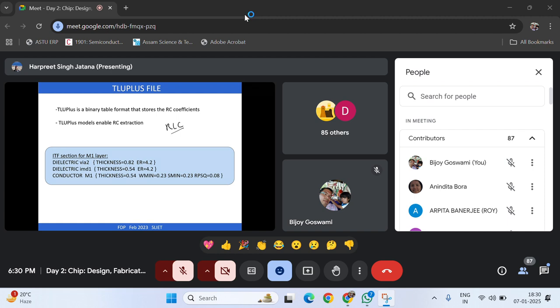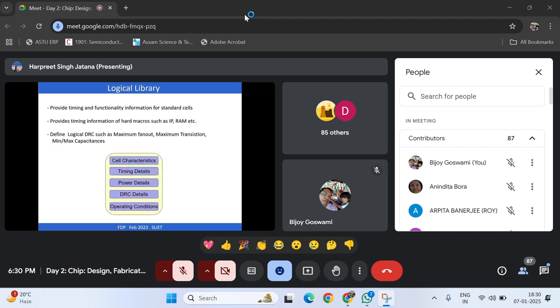Once you do the coarse placement of these blocks and you do the routing, you know the length of the nets, and you know the RLC per unit, so you can calculate the total RLC. So that is RC extraction, because inductance is also important below 90-45 nanometer. Those things you can do, and then take into account to simulate the circuit using parasitics of the interconnects.